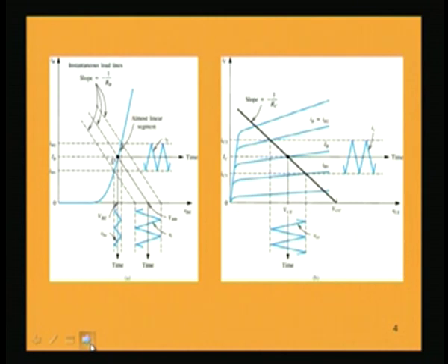So, now again if we look into the AC and DC components and the overall instantaneous currents and voltages, then we see in these plots, when only DC conditions are prevailing, suppose we are not giving the signal as such till now, only the biasing voltages are there, then due to the DC biasing, the input circuit is forward biased and the output circuit is reverse biased.